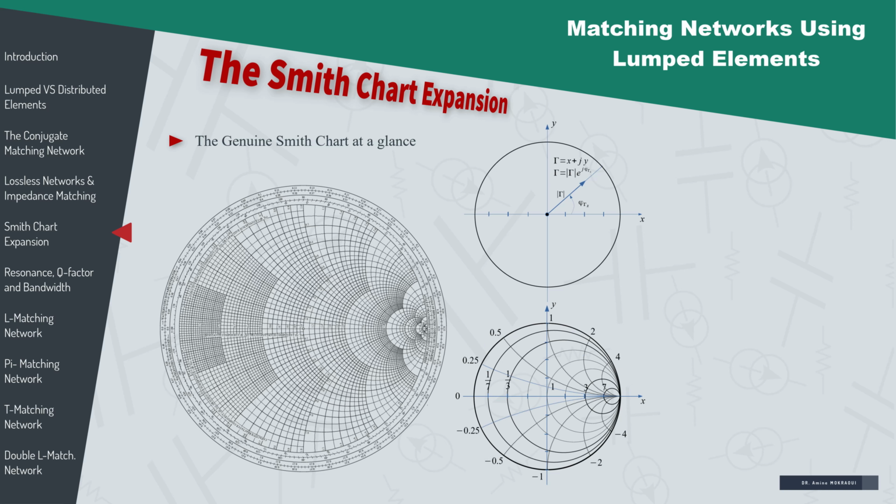The Smith chart relies on the use of a normalization impedance Z0, which is smartly chosen to ease solving problems. It could be the characteristic impedance of a transmission line, the load resistance, the internal resistance of the generator, or any other resistance which allows getting accurate results. In this video, we will use lowercase letters to designate normalized quantities. For example, if uppercase Z equals R plus jX, then lowercase z equals Z over Z0, which is equal to lowercase r plus jx, where lowercase r equals R over Z0 and lowercase x equals X over Z0.